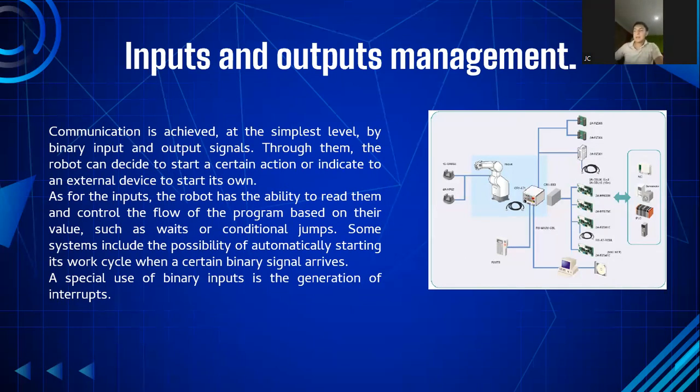Another important application of the robot inputs and outputs, whether digital or analog, is the integration of sensors, incorporating their information into the task. Above all, sensors allow certain applications to be carried out in a partially unknown environment or with some degree of uncertainty, such as, for example, the precise location of a part.